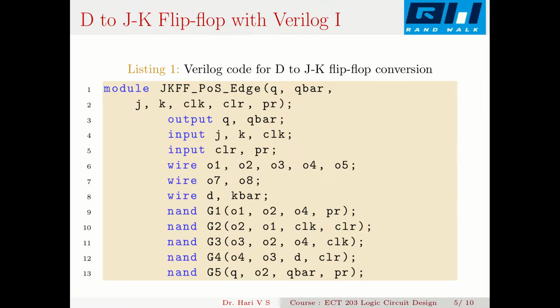These lines create a D flip flop with a clear and preset. So this way you can realize its outputs Q and Q bar. So this realizes the JK flip flop with a D flip flop.